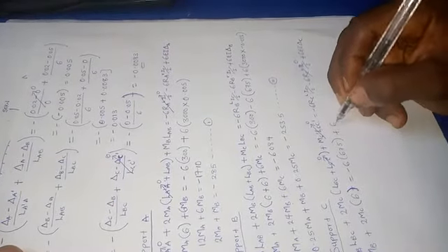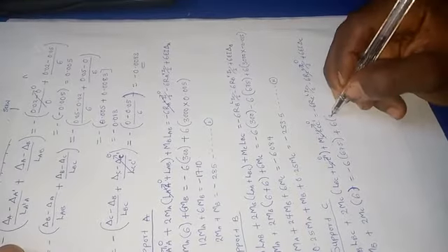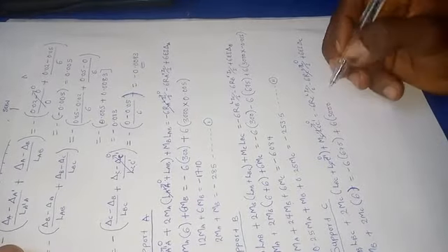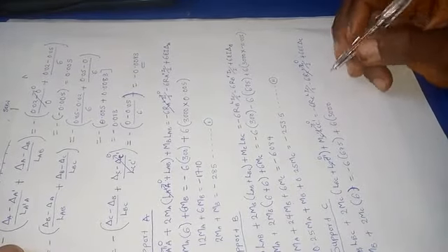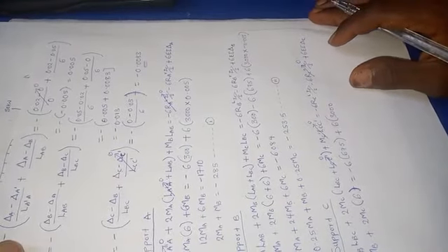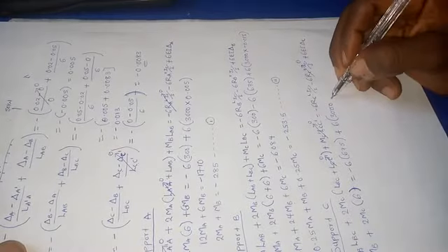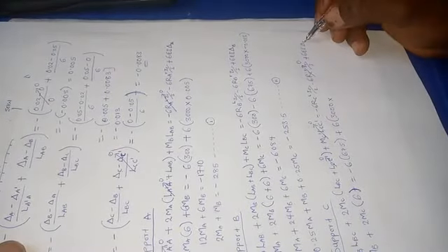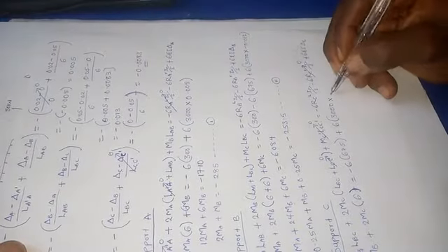Then plus 6 in bracket multiplied by my EI, which is still 3000 from our question. Please don't get confused. You can ask any question on the comment section and I'll reply later. So this is 6 times 3000 times the settlement at C we calculated as minus 0.0083.